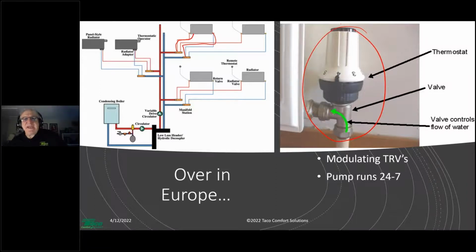If you were to do the math, I remember we talked about delta T. Typical European heating systems like this are designed around a delta T of about 38 to 40 degrees. With a wider delta T, you've got a big old panel radiator, so it can work with that wider delta T with no problems. But that results in, relatively speaking, low flow rates. If you're trying to deliver 50,000 BTUs at a 20-degree delta T, that's 5 gallons a minute. If you're trying to do it with a 40-degree delta T, that's 2.5 gallons a minute. Lower flow. We're still running very small diameter pipe.